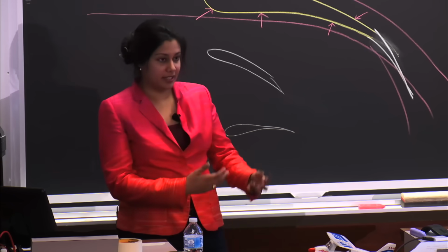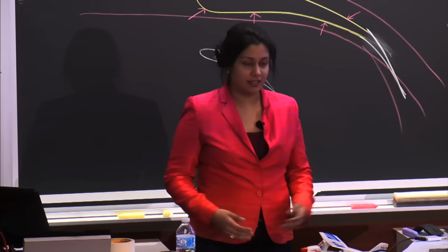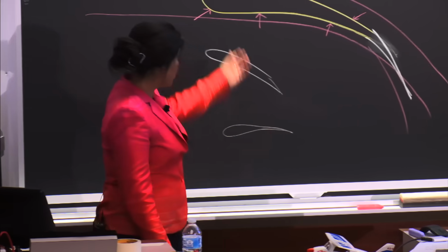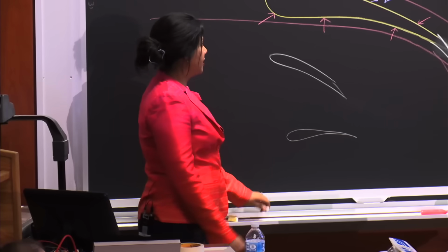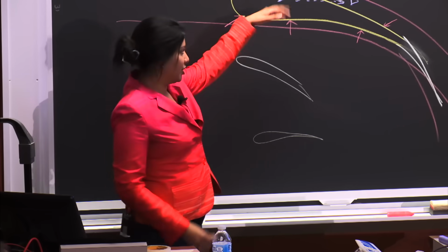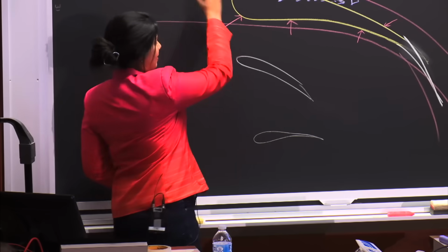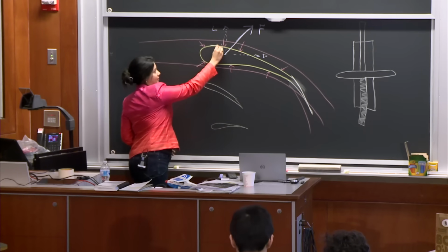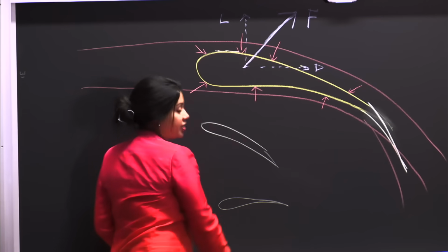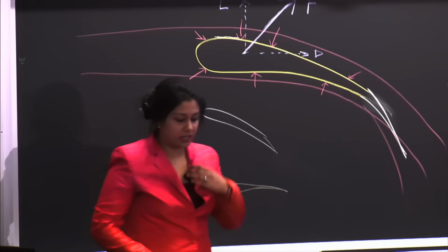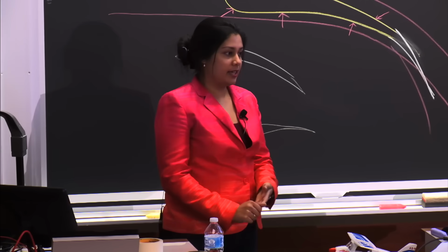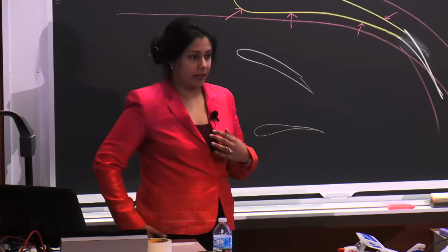So it's the tendency for these molecules to stick to each other and to stick to the object that's moving through them. With the case of the airfoil, and we were discussing this just a moment ago about which air we were talking about, some air that might be very close might stick to that airfoil or stick to the wing versus just moving smoothly past it. So viscosity has a big impact. And then compressibility also affects lift. So the compressibility of the air.